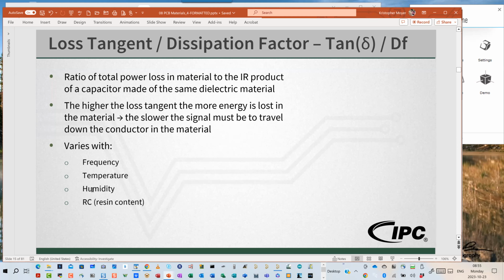Just like we were talking about with the glass transition temperature, as the board material gets hotter and hotter, that resin starts to soften up. It tries to go back to phase change. When it's fully cured, it'll never go completely back into the liquid state, but it does soften. The softer that resin is, the more it will dissipate or absorb energy. It'll have that spring force, right?